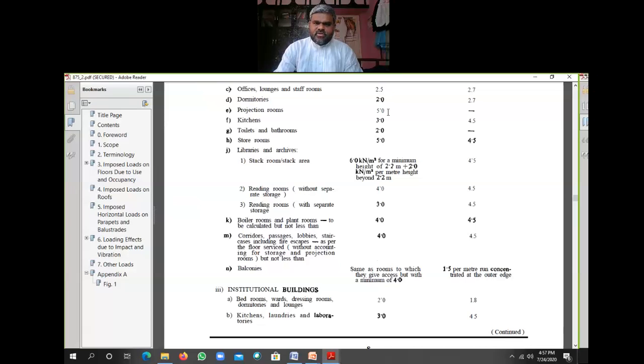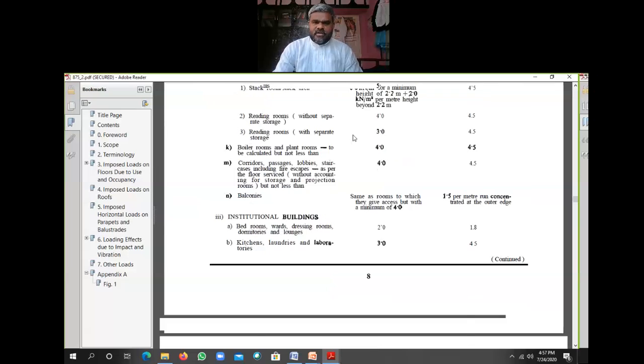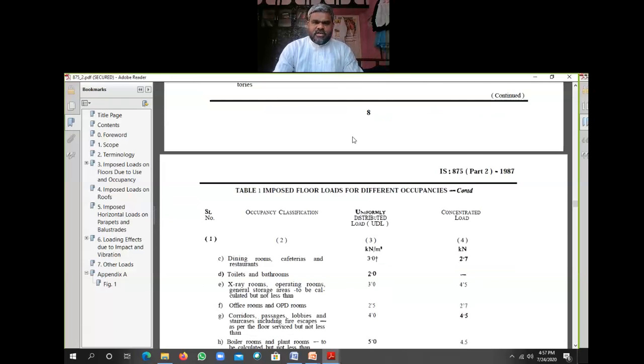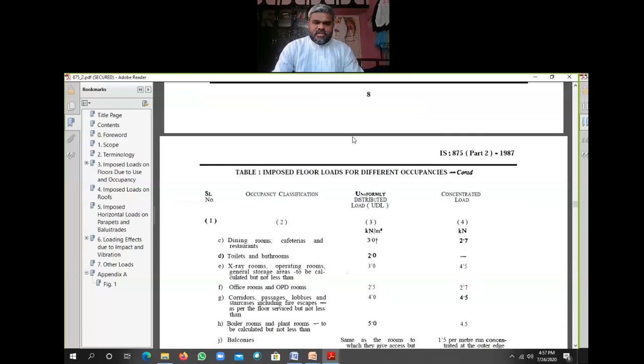These are all included in the calculation so that the total load arrived at is called the imposed load on the educational building, right? So dead load we can calculate from unit weights of materials, and live load we can calculate from the code, like for institutional buildings, right?